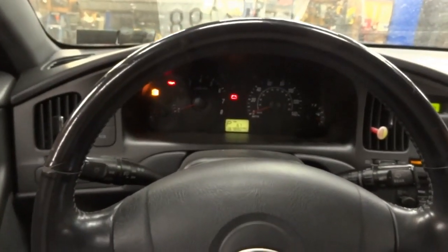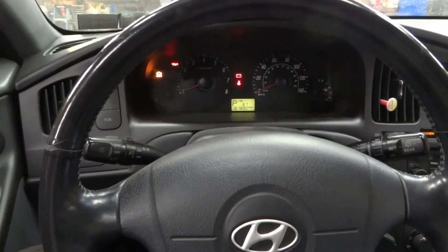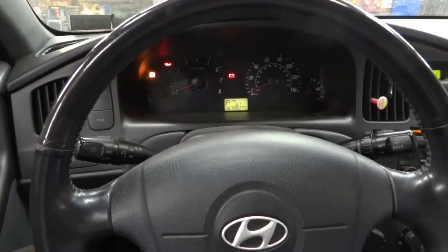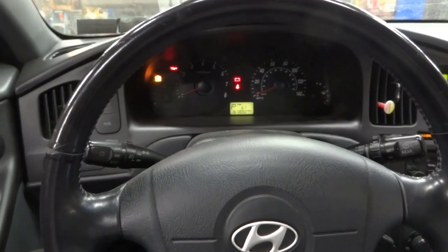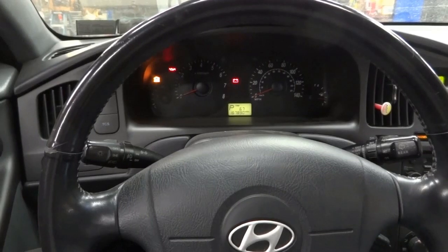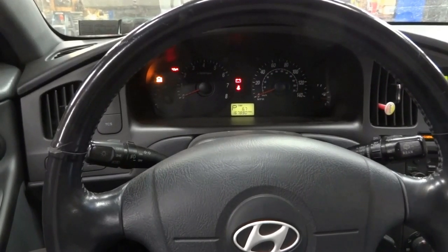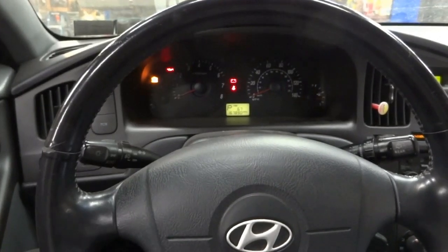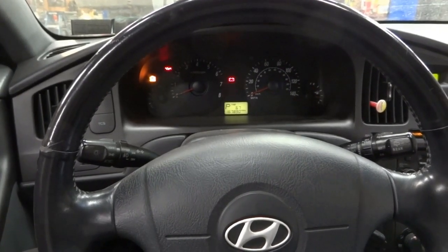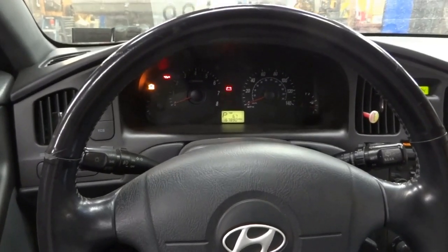So knowing that we cannot go over 25 miles an hour, the engine is losing power, there's no check engine light on, we have low mass airflow sensor values at high RPMs, and high negative numbers on the short-term fuel trim at higher RPMs, that tells me that the issue is the exhaust, a clogged exhaust. So we're gonna check that really fast.